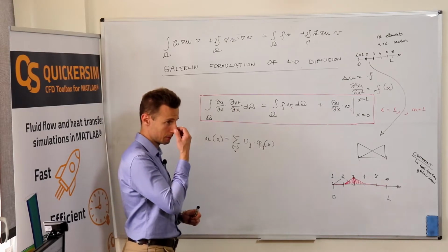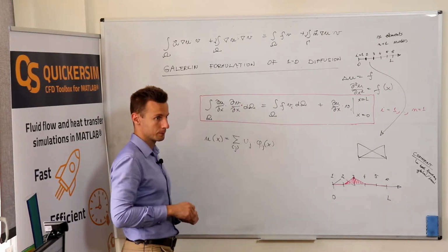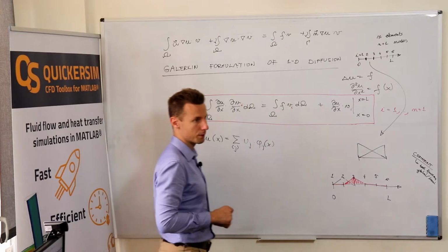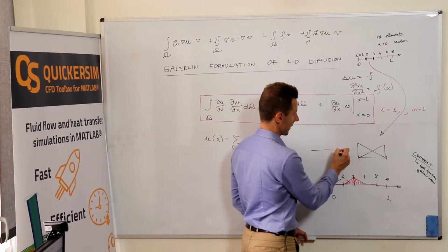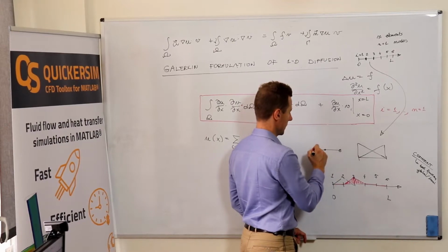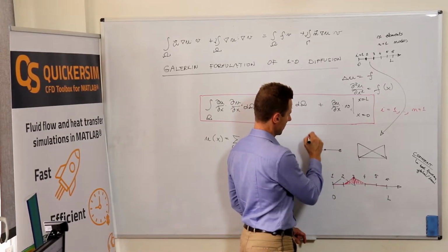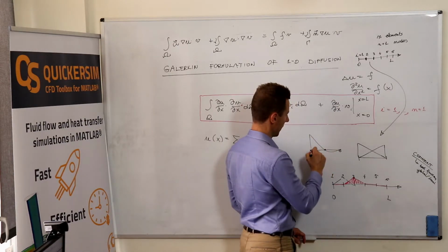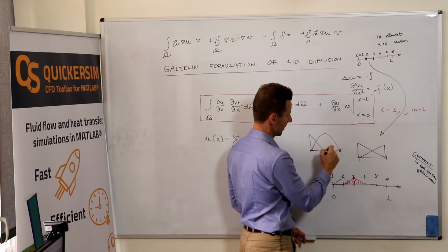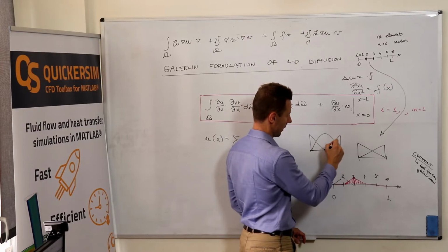That's true as well. And what about second order meshes? There is no problem with that, because if you define the second order finite elements, you've got, well, one shape function would look like that, the other would be like that, the third one would be like that.